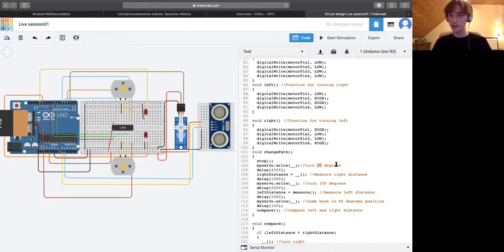For example, if you experiment with a real robot, you may see how you tell the servo to position itself at 150 degrees, but instead it positions itself at 180 degrees. And if that servo can only turn from 1 to 180, it can basically break your servo. So this is why we're using 30. Also, as we turn to this, we use a measure function.